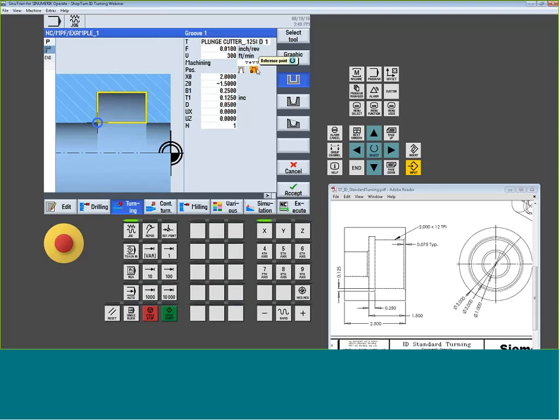The next indicator controls dimensionally where I know the groove information from. So this is going to relate to our print. If I look at the dimensions, I was dimensioned from the face to the back edge, and then my width came off that. So it's only logical for me to use the point that's on the lower left side. I could use the point that's on the lower left side but in the deepest part of the groove, especially if I had a taper to it, that becomes critical. I could use the other side, the right side, on either side of the groove position. So we're going to use the lower left corner, and now you're going to give it some basic geometry.